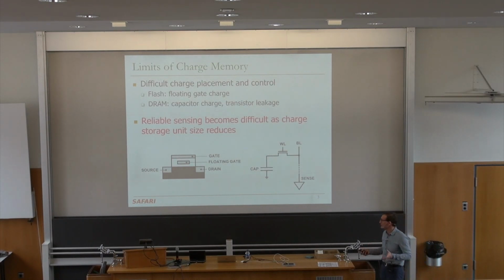That's a non-volatile memory technology that's still charge-based, and here you actually store the charge inside this floating gate, and whether or not you have enough charge determines whether or not you have a 1 or 0 over here. Very similar to DRAM, but it's a very different mechanism, of course, as you can see. There's no capacitor here. It's really based on a floating gate that traps charge internally.